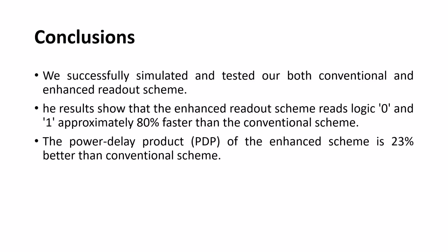So in conclusion, we have successfully simulated and tested our conventional and enhanced readout schemes. The result shows that the enhanced readout scheme reads logic 0 and 1 approximately 80% faster than the conventional scheme, and the power delay product is 23% better than the conventional scheme.